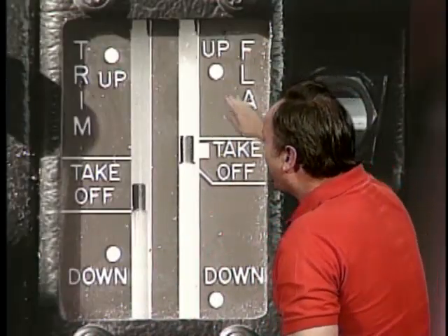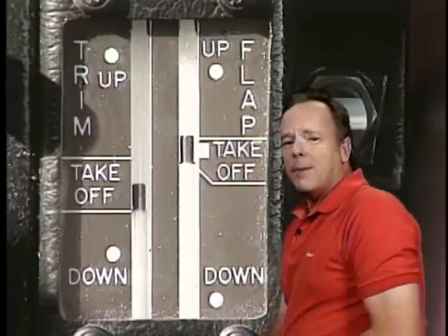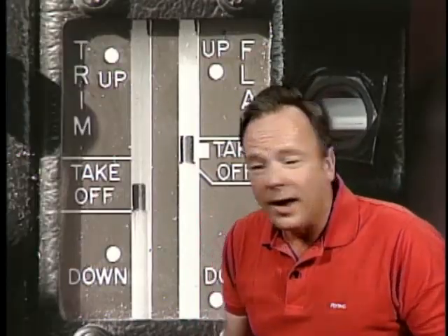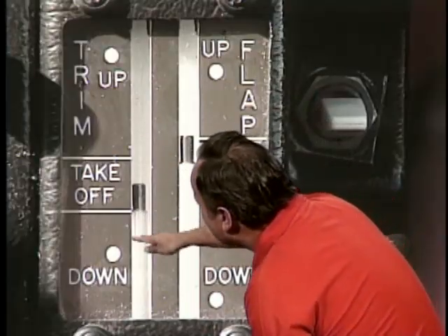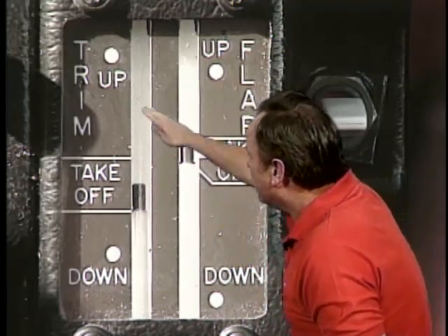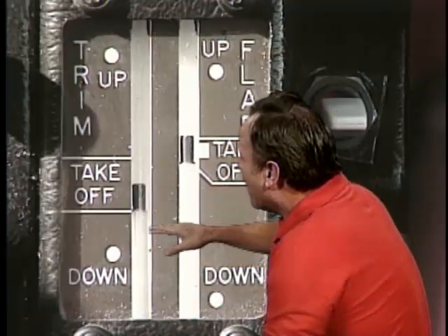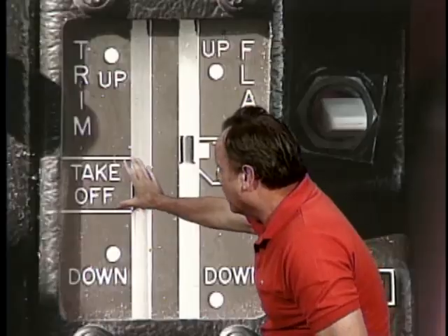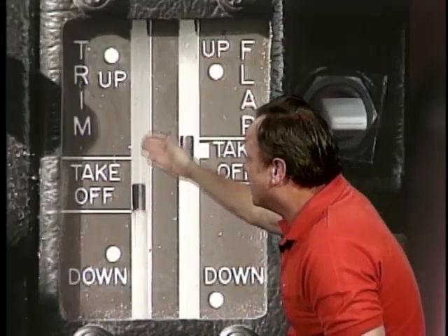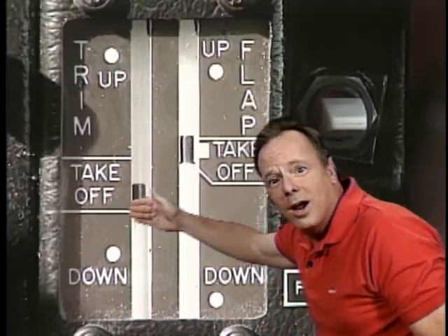So if you have a flap indicating system, indicates the flap position, does that have anything to do with the primary control surfaces? No, it would not. How about a speed brake indicating system? No, it would not. How about elevator trim indicating system? Does that have anything to do with the primary control surfaces of the aircraft? And the answer is yes. Elevator trim indicating tells you the proper trim position for instance, takeoff in this particular case, or maybe landing. And it has to do with the primary control surfaces because the elevator is one of those primary control surfaces of the airplane.